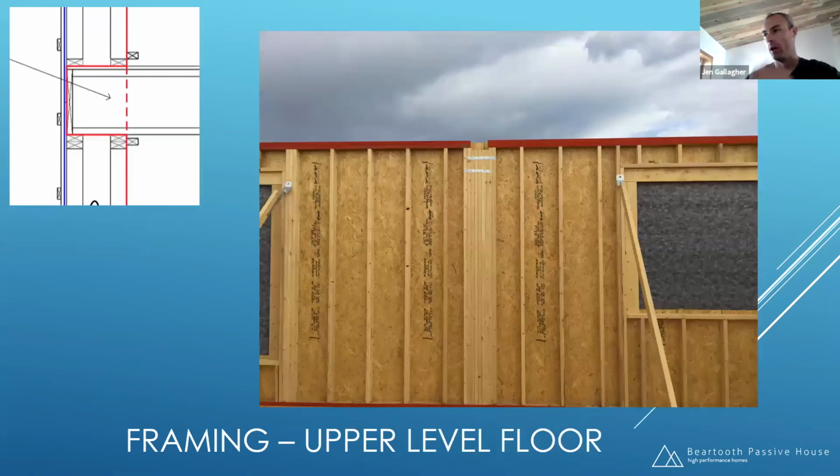Okay, so I mentioned on the air barrier stuff that the trickiest transition for us was taking the air barrier from the first floor walls to the second floor walls, and we had to do that out and around the floor joists because our exterior wall was structural. So this is the main floor wall. This is the beam pocket that we had built that will accept one of the big 7-inch wide by 18-inch tall laminated LVL beams that carry the second floor wall.